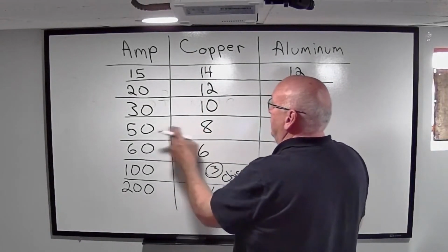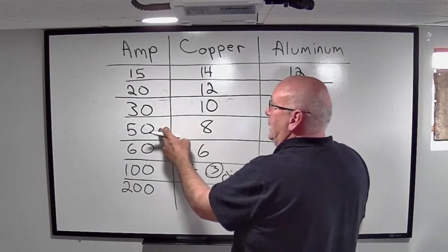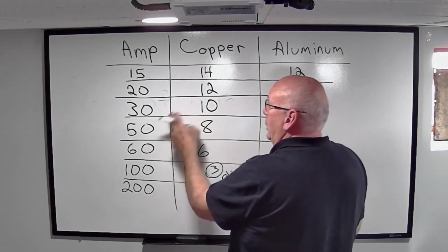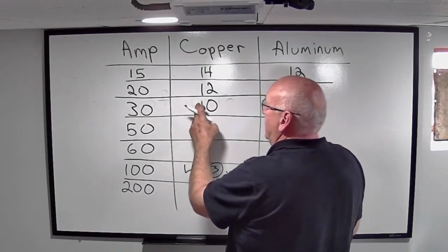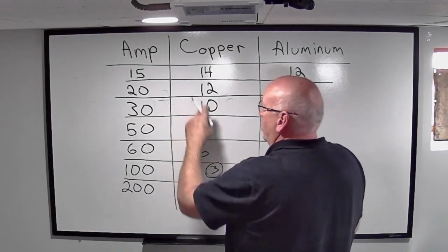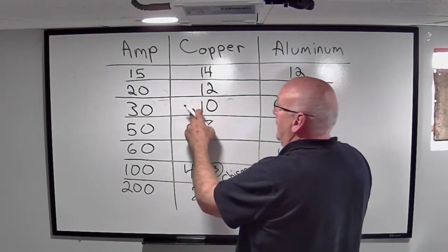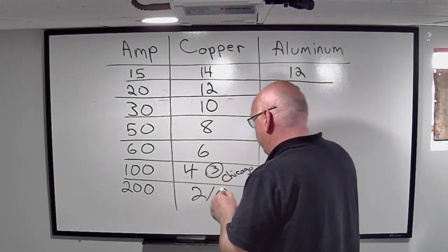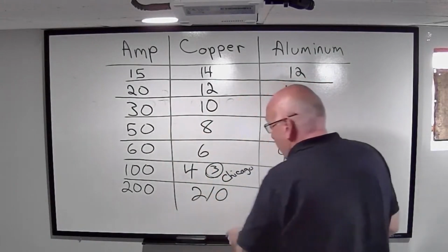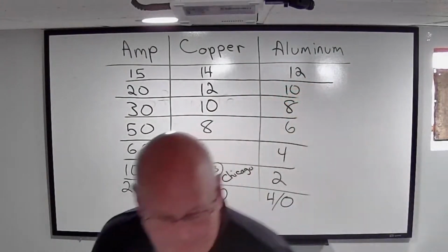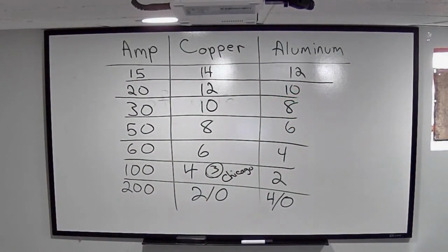Whatever breaker can protect that, that's what I can go ahead and use. So I'm going to go back to the slide drawing in a second, and that's at 125%. But if I had a number 10 copper wire on a 15 amp, or I'm sorry, on a 50 amp breaker to go ahead and protect everything.